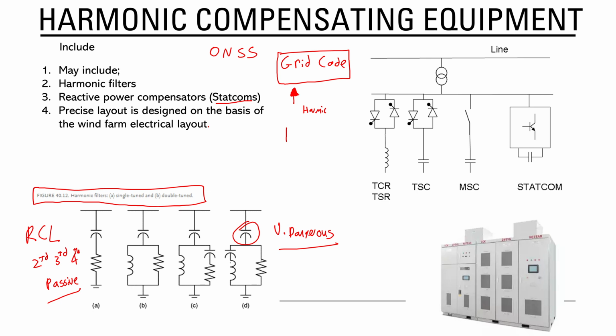Now, reactive power is a little different, and that requires a certain amount of active control. So if you remember, we have a power triangle where we have true power along one side and reactive along the other. Then the total amount of power is the volts times the current, but the true power is VI cos theta, and that will always be less than 1 if there is any degree of reactive power in the system.